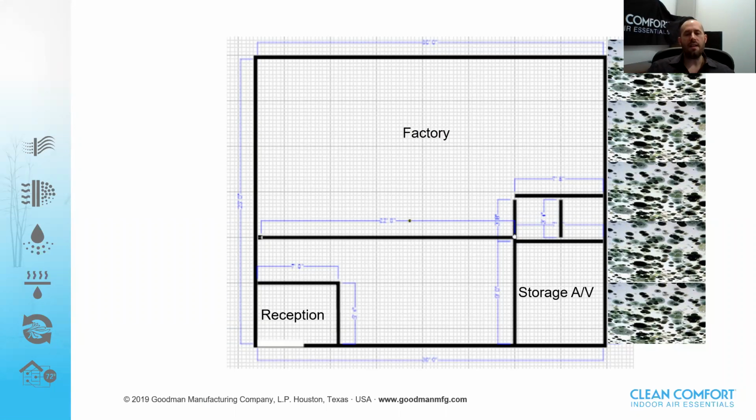This was an abandoned factory. And after they redid it and moved in, they had extremely high relative humidity. In one wall was growing mold. The process they used included water in part of the production. And we were seeing things like 80% relative humidity. So here we used a bunch of dehumidifiers and we also used air purifiers.